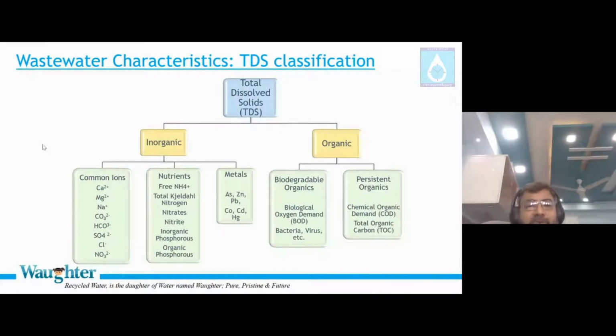What is called TDS, total dissolved solids? Technically, in the books it is written as two terms called inorganics and organics, sum of both. But most of the time, TDS actually is only because of inorganics, because organics do not contribute to conductivity. I'm presenting this slide because this is the way you will see it in the books. But when a layman or a water treatment technocrat talks TDS, he actually means only inorganic solids. He doesn't mean organic solids. Traditionally, dissolved solids means both inorganic as well as organics.